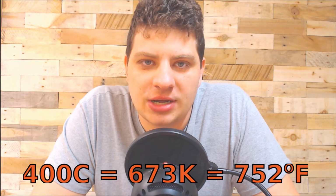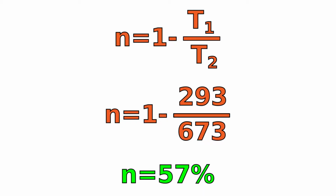If you use those numbers and plug them into the equation we talked about earlier, you end up with a thermal efficiency of 57%, which really actually isn't bad. That is actually higher than a normal internal combustion engine. Unfortunately for us, running at 400 C results in a very melted and probably on fire engine. So we need to keep the temperature lower.